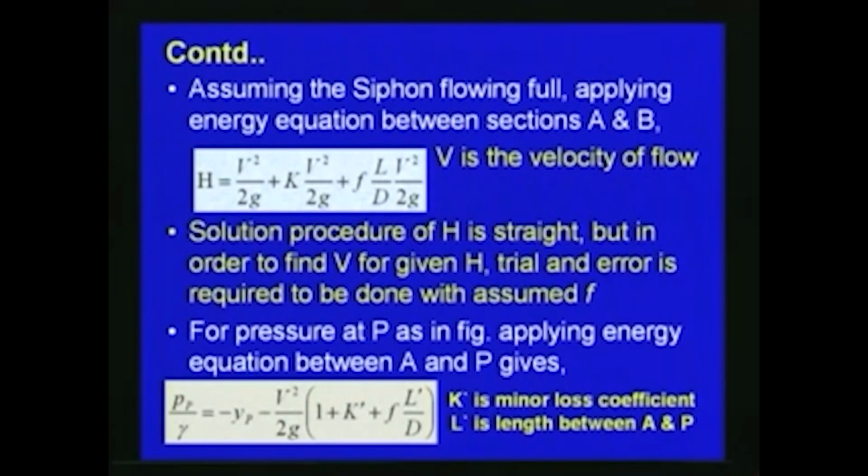Simple analysis we can do, since here what we have to find out is either the pressure at the elevated location, or how much liquid has to be transferred, or the head loss in the process. So, different kinds of problems which we discussed with respect to the pipe flow systems are applicable here also. So, we can use the simple Bernoulli's equation, and then we can also use the continuity equation together to get the various parameters with respect to the siphon.